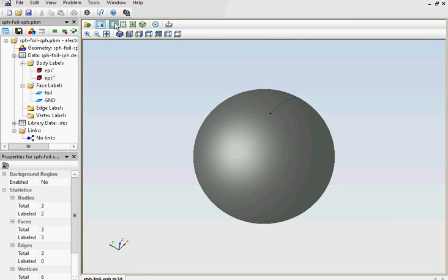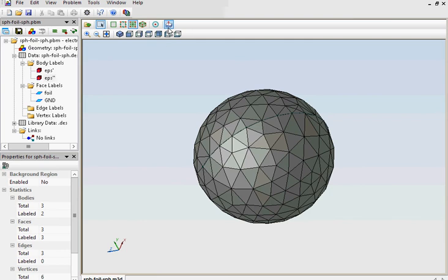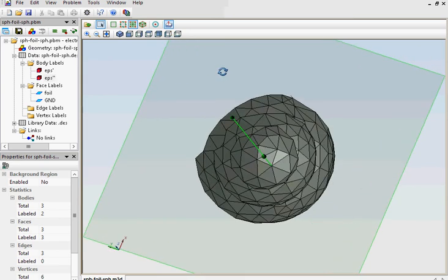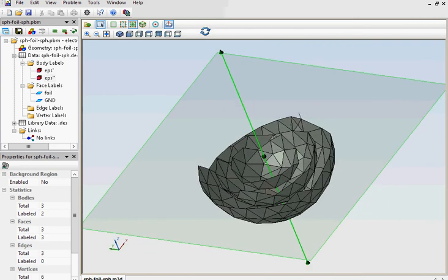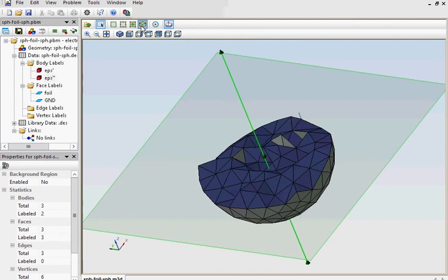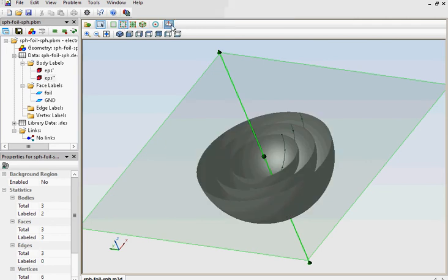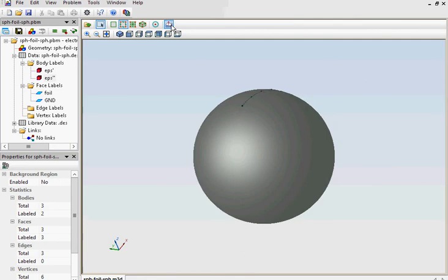The mesh is generated in 3 stages. First, the edges are subdivided. Then faces. If you look inside, you will see that only faces have the mesh now. And the last step is volume meshing. So the meshing starts with edges, and you can attenuate the mesh in the edge vertices.